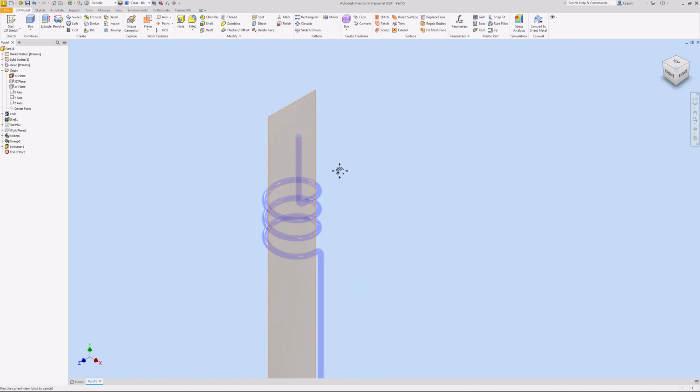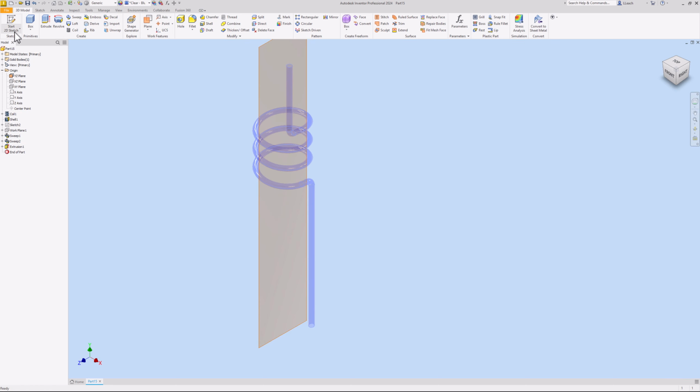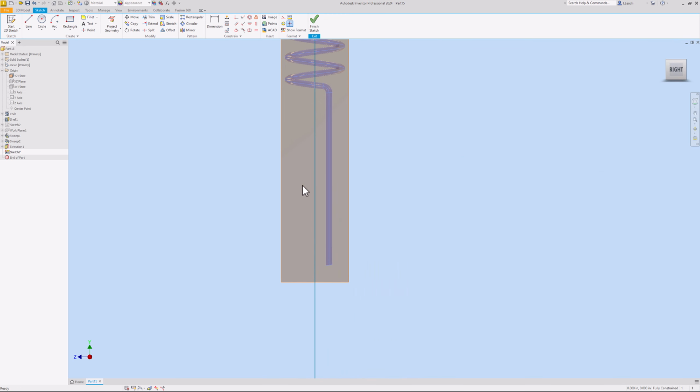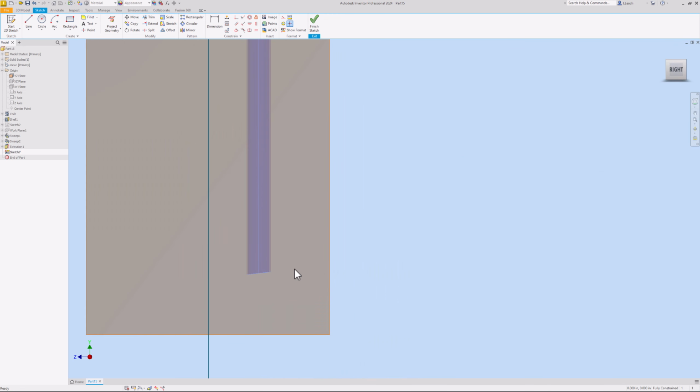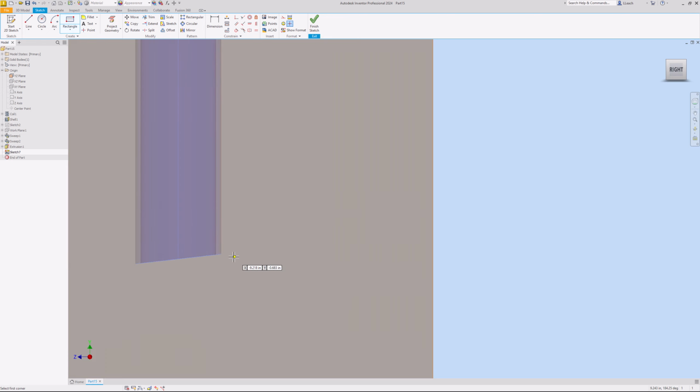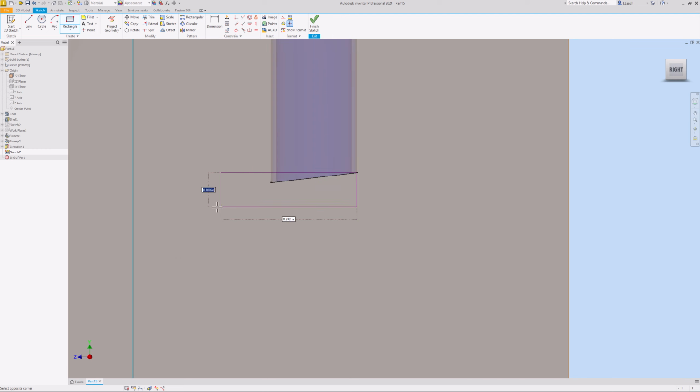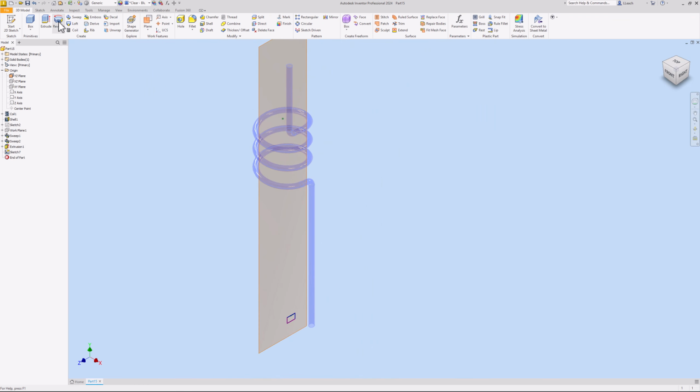And I did the same thing for this bottom one, so start a 2D sketch on this one. I guess I could have done both of those in the same sketch, but let's go rectangle, 2 point. I'm going to select this side here, drag it over and down, finish my sketch, and extrude that little shape that we made.